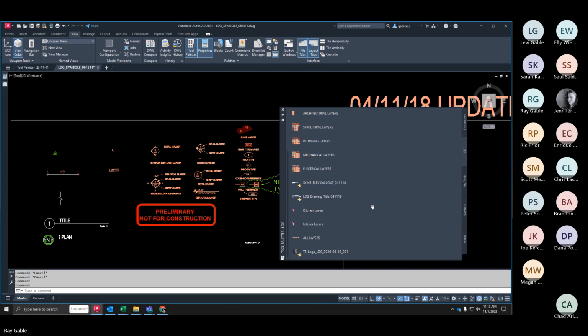Okay. And then you touched on the symbols, and I think the symbols are nice. I mean, we do have them on the front page. You can copy them out. But what I like about these palettes is that these symbols go on and that they're all one-to-one. So when you drag a symbol into your drawing, all you need to do is right click on it, give it the appropriate scale factor, and then you're off and running.